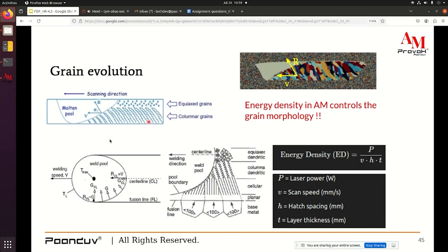During the solidification process, additive manufacturing being a rapid solidification process, it allows the grains to nucleate preferentially and faster as compared to other manufacturing processes. The nucleation and grain growth is primarily favored by the temperature and the temperature gradient itself. The higher solidification rate in combination with the temperature gradient allows the formation of different grain morphologies.